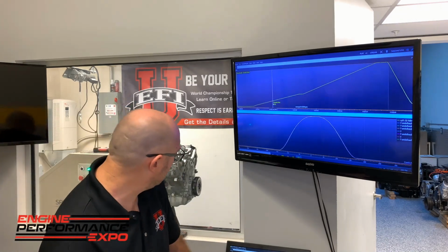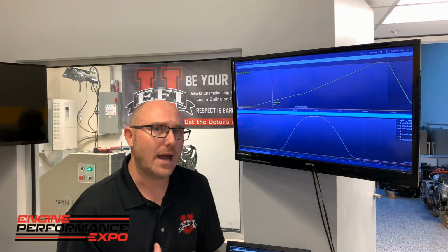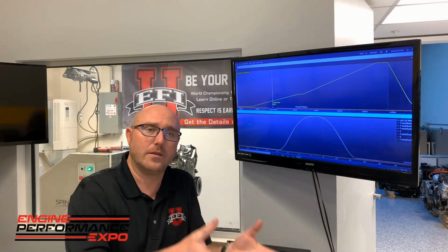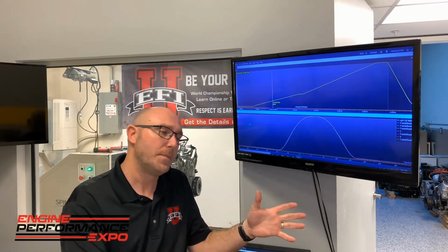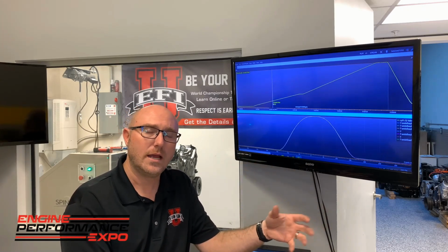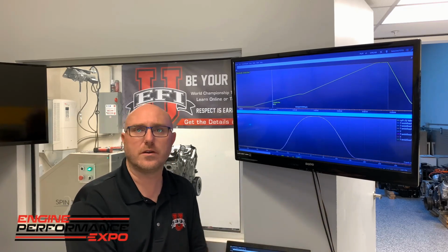So behind me, you see some of the pieces of it, and we'll go in there and look a little closer in a little bit. But it's about the opposite of what you would expect from a dyno. Typically, we build the engine, and we put it on the dyno, which is a power absorber, and we run the engine, which spins the dyno. The dyno creates load, and it records things like power and torque and RPM and all sorts of other data.